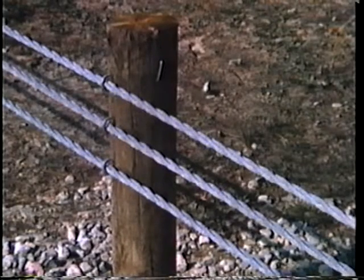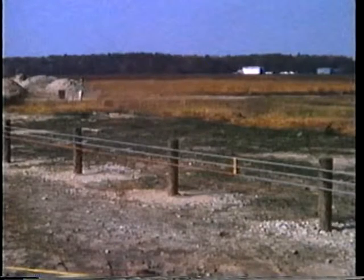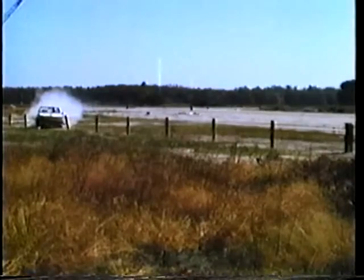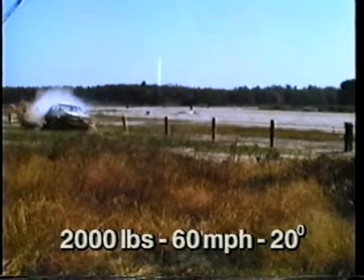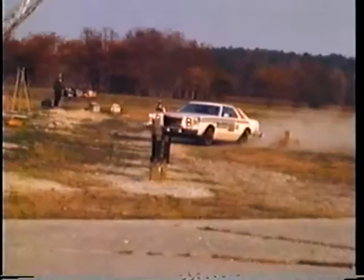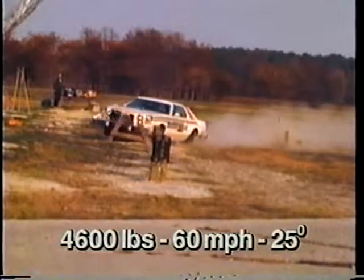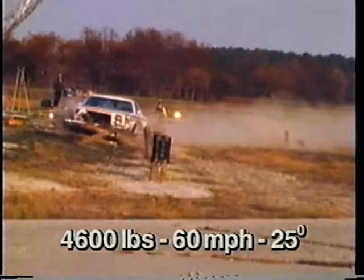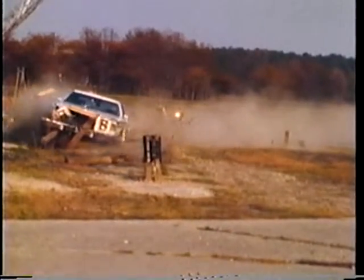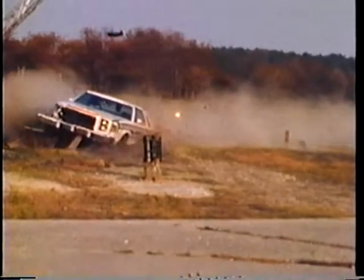This hole helps to weaken the post in the longitudinal direction, ensuring that it breaks away when hit head-on. The post spacing used is 12 feet 6 inches, rather than the 16 feet as is typical for G1 systems. This small car was successfully redirected without exceeding the allowable occupant response values. The system was also strong enough to contain and redirect this large passenger sedan. The maximum barrier deflections were comparable to the standard G1 system in these two tests.